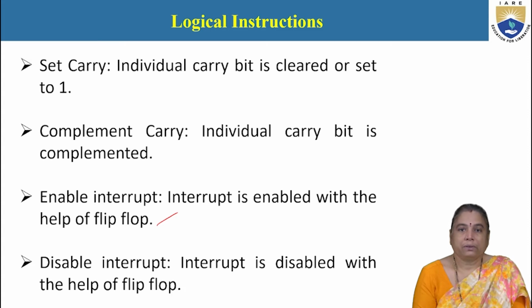If an interrupt is raised, the program stops its execution and temporarily suspends the current execution of the program, and it transfers the control to the interrupt service routine. The interrupt service routine instructions are executed one after another until it finds the return statement. As soon as a return statement is encountered, the control returns back to the main program and resumes the program execution.